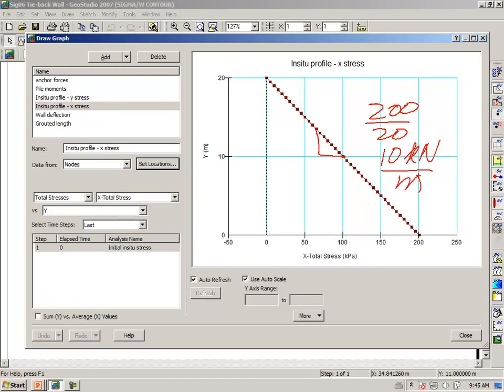Or we can think of it as a fluid pressure of 10 kilonewtons per meter cubed. It's a rate of removing stress that is referenced to the top here. This is where we will reference the elevation here, and then the stress that is applied on the face of the excavation depends on the distance here, what we need to reference ourselves to the ground surface.